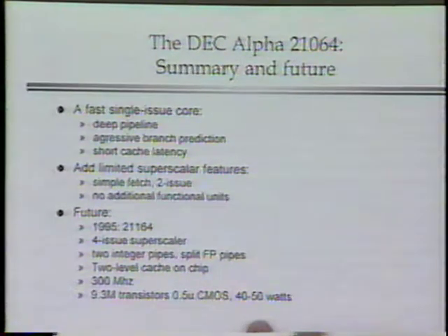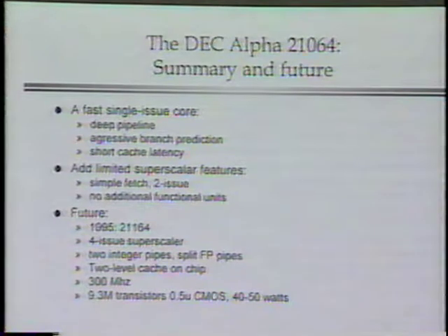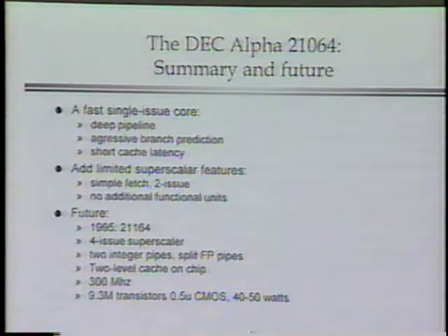It also has a consequence on the circuitry that surrounds the chip. The fact that the clock is that fast means that everything else surrounding the chip and the clock generation circuits has to be high performance, high speed, almost microwave design techniques. The memories have to be extremely fast. This certainly is a technique for making a very high performance computer, but it is not without cost. It's unlikely, for example, that you're going to be able to put a 21164 into a laptop computer because the power dissipation and heat generation is just too extreme.